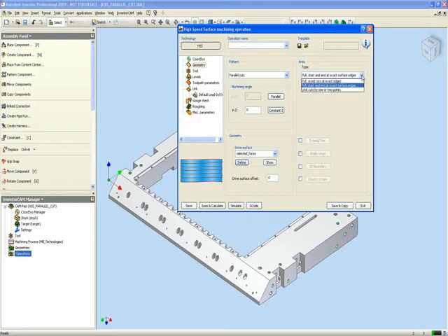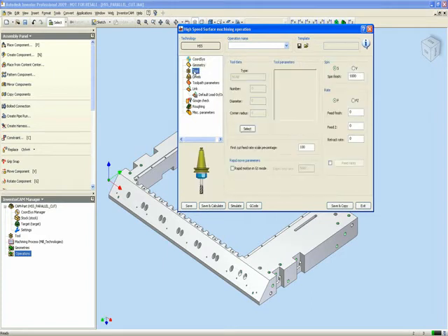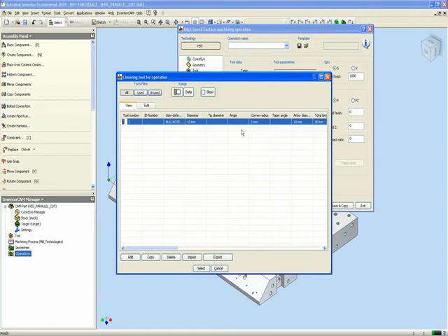One more option we also have is that we can limit cuts by 1 or 2 points. By simply picking a point on the surface itself, I can limit it to work between those 2 points only. In this particular case, I want to use the option of full start and end at exact surfaces. Next, I must pick a tool, and the tool I will be using will be a bullnose tool of 10 millimeters with a 1 millimeter radius on the corner itself.